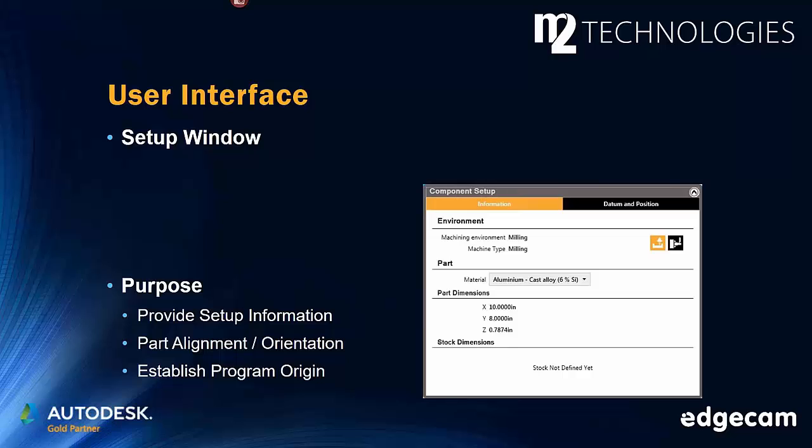It provides part setup information such as the material we're cutting, the dimensions of the part, and then once we put in stock, the dimensions of the stock that was added. It also allows from the Datum and Position tab for very fast part alignment and orientation and establishing where our program origin will be. Really useful command. It saves a ton of time at building the virtual CAM setup so that we can quickly get to the machining tab where we want to do our work in the CAM system.